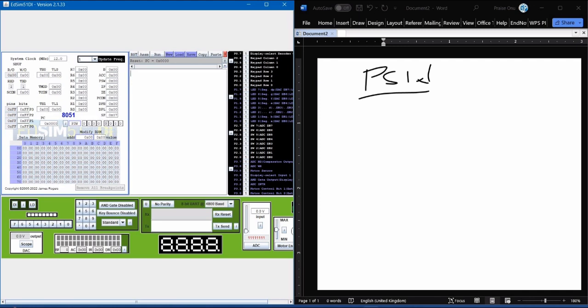When you're dealing with memory organization, you actually see how the register banks are. These two bits are used to indicate which of the register banks is selected. Then you have the overflow, and you have this particular one, which is a reserved bit, it's just reserved, not used. Depending on the operation being carried out, if you require more bits, you can use this bit. And the least significant bit is called the parity bit.